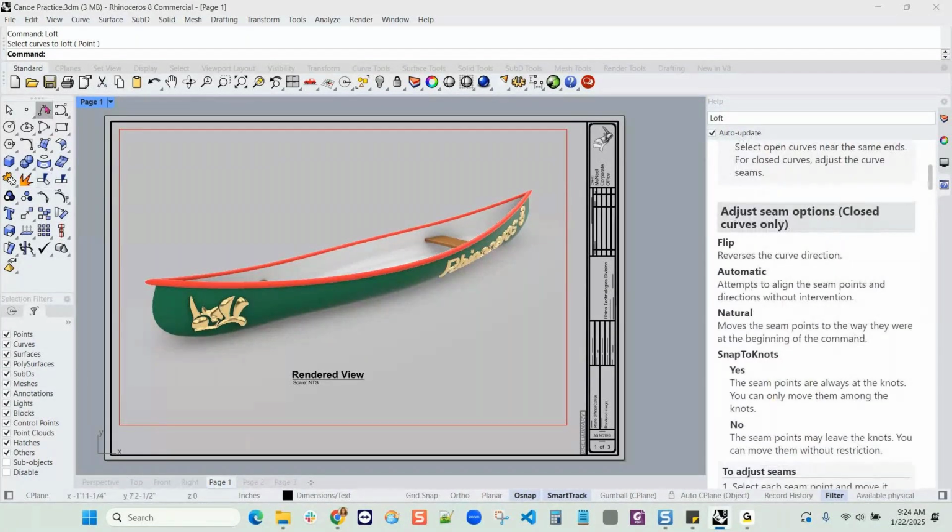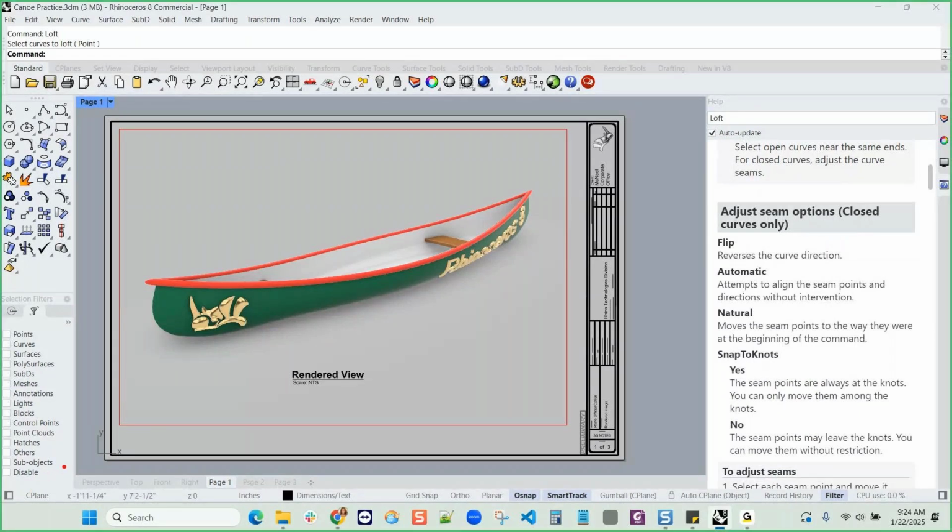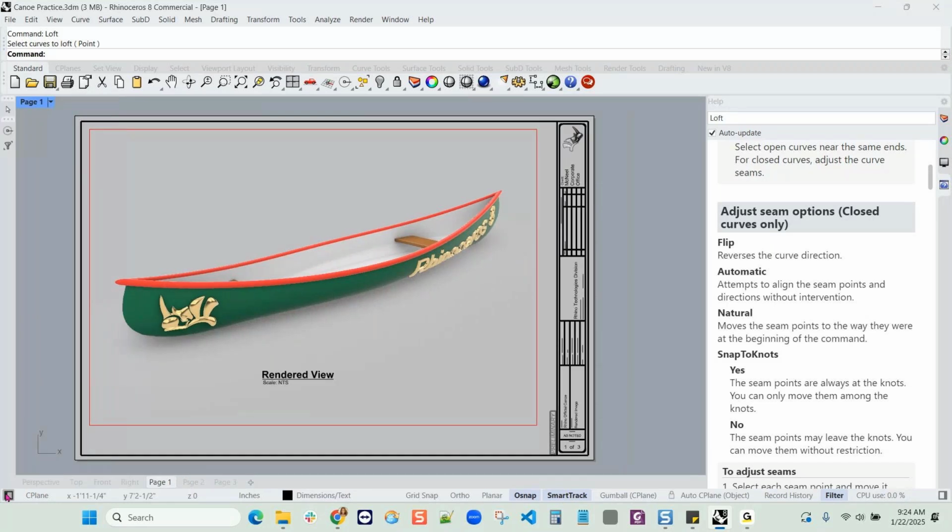The sidebar in Rhino has a new option in Rhino 8, and it's a button that will collapse and show the sidebar. So if you pick on this button, it will reclaim that area of the screen and basically just close up the sidebar.